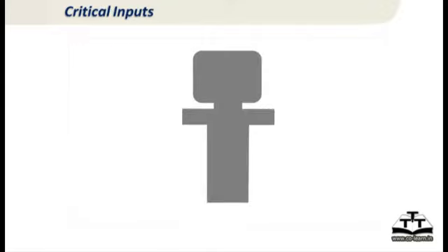So let's just quickly review. What are the inputs which really make a difference to the simulation? Number one, I must have the correct part geometry. You can't have a machined part for simulation, you must have an as-cast part for simulation with all the allowances and drafts. But very critically, if there's a drill hole, you must remove the drill hole. That's what creates maximum error in a simulation.